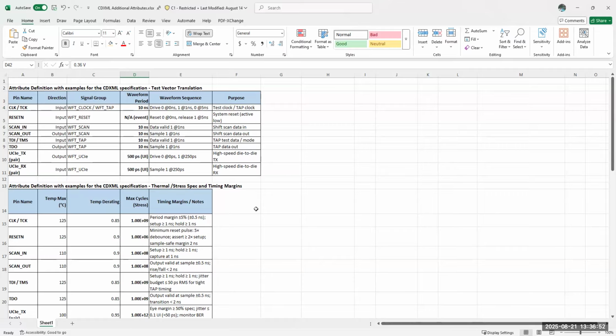So when you want to do this at SIP level, you don't have to do 2-pass retargeting. In Siemens, it supports the flow. You can directly take any partition and retarget to the SIP level. You can bypass the chiplet if you want. I see. So that is a new tool enhancement which understands the PTAP and STAP.